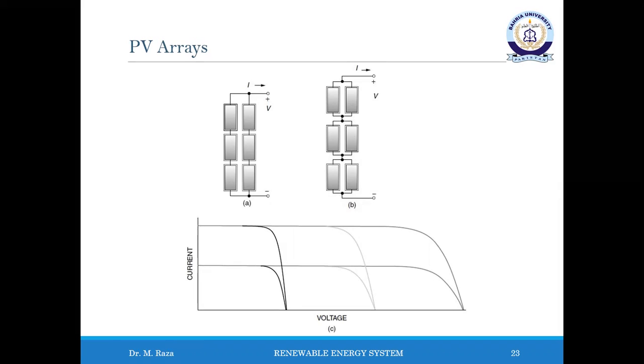There is a reason, however, to prefer the wiring of the strings in parallel. This topology is preferable because if an entire string is removed from service for some reason, the array can still deliver whatever voltage is needed by the load, though the current is diminished, which is not the case when a parallel group of modules is removed.